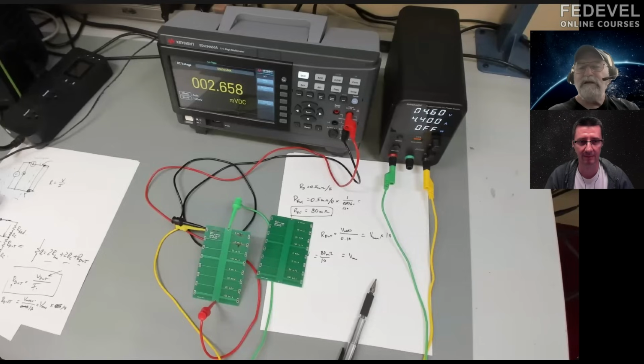You often want a low value resistor so that you don't get a large voltage drop. But it means you're going to measure small voltages. And so you'll find a lot of small value sense resistors have 4 leads coming off. They're designed to send the current through 2 leads and measure the voltage across the other 2 leads.